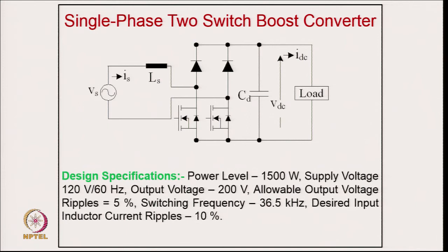Another benefit we discussed is that you are able to get quite fine control up to quite a low level. And the third is that the losses are reduced by 50%, because now there are only 2 devices conducting at a time. Along with the diode conducting, or along with this MOSFET, typically with this switch you have a diode conduction also. So that is typically the benefit of it, and people have used it.